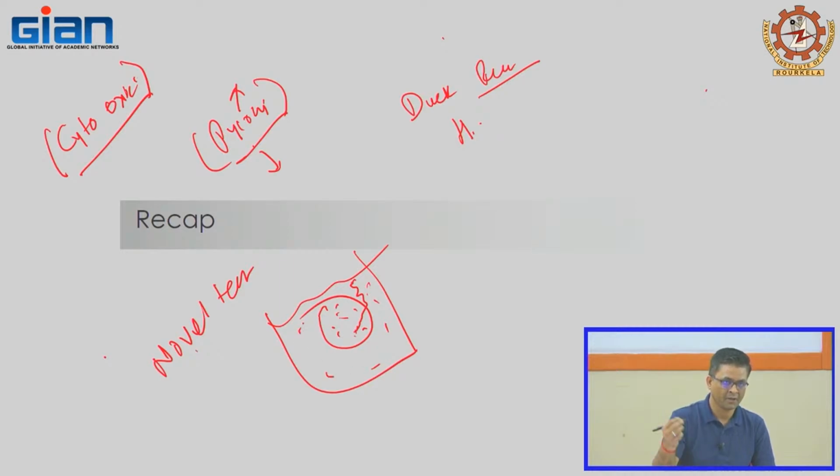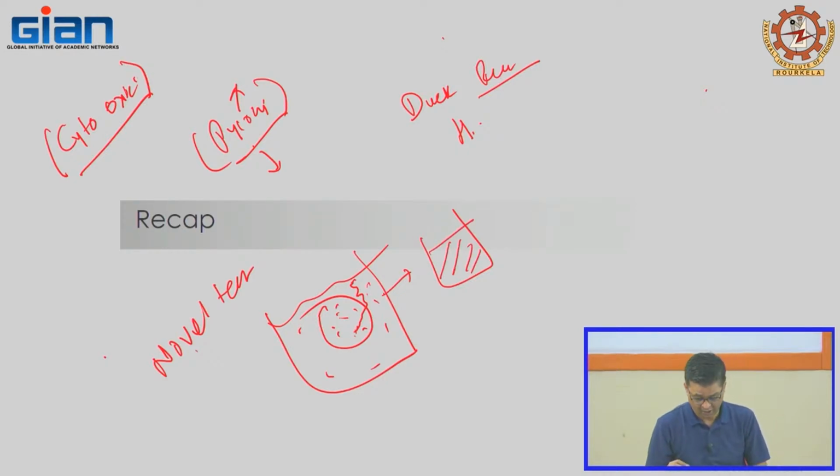You centrifuge it, the residue is out, and this is the extract. Now, you collect it from this extract. When you use ultrasonic, for example, what it helps in is allowing the solvent to get into the biomass. It is not only for the temperature side of it, but also to improve the diffusion.